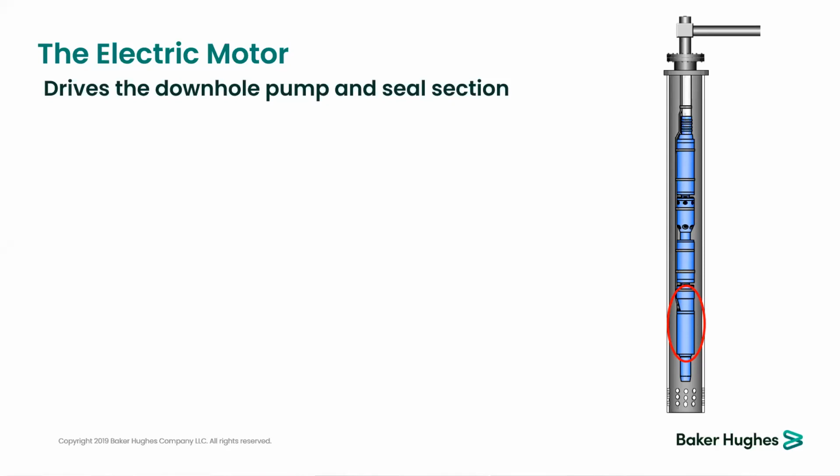It is constructed of rotor and bearing stacked on the shaft and loaded on the stator. The motor contains a synthetic oil for lubrication and relies on the fluid flow path across the motor for cooling of the motor itself.